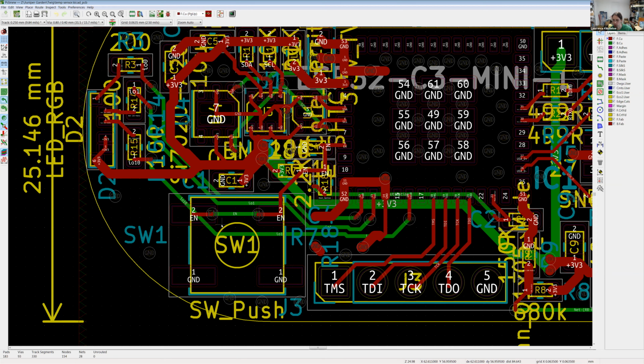But if you do a long press, it'll reboot the device. And if you power it on normally, it'll just reboot the device normally. The problem is that it uses a resistor divider network, and it also uses a capacitor and the charge rate of the capacitor to configure the timing for the whole circuit. And so it's very dependent upon temperature and upon the value of your resistors and capacitors.